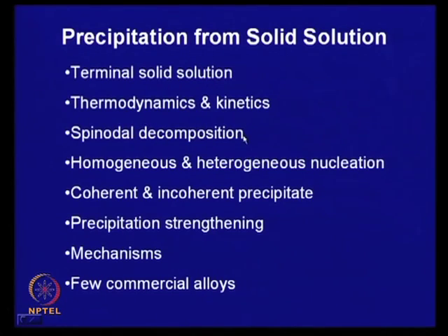of precipitation, we will learn about spinodal decomposition, we will look at homogeneous and heterogeneous nucleation, we will also learn about the types of precipitate that we come across, and the main purpose of all this is to get some additional strengthening in the material. So, we will look at precipitation strengthening, the mechanism of strengthening, and we will learn about few commercial alloys.